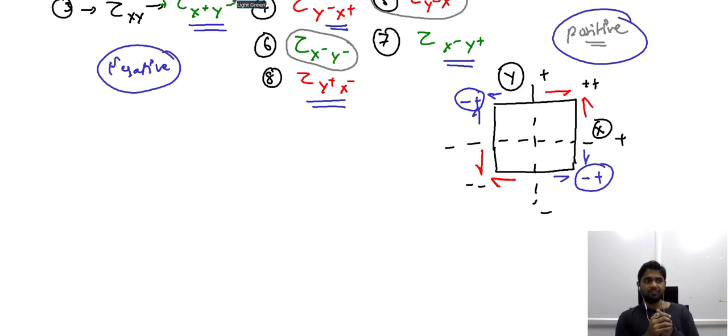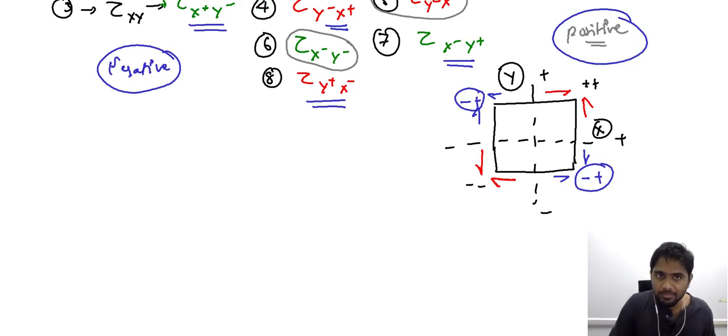So what essentially we have arrived at is a relation established between the shear stresses, and in addition we have now understood the convention associated with the shear stresses. So when we have shear stress experienced by a given element, a given sample, then we can use this representation here. When the direction along with the plane are part of the positive quadrant, so these are referred to as the different quadrants, when these are part of the completely positive quadrant or the completely negative quadrant, then we refer to those shear stresses as the positive shear stress.